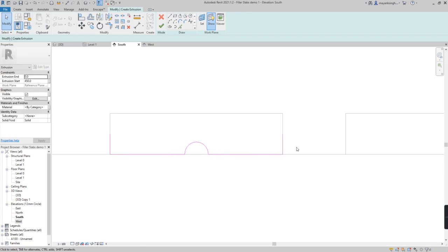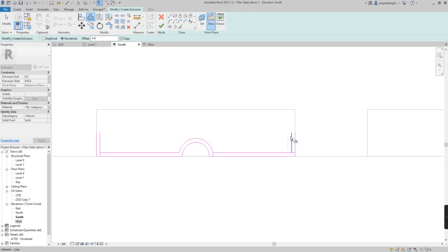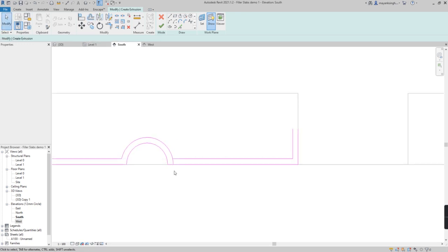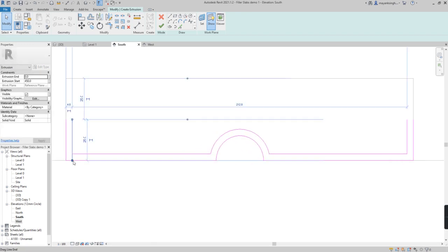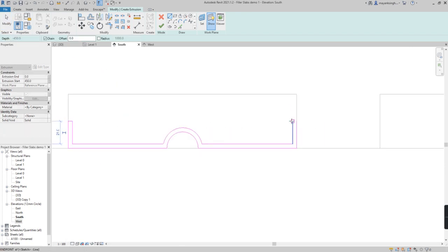Now this is nice, I will create a small offset for the thickness. Again, I'll go with 4 mm, and this is it. I'll pull back, make a proper fillet, close it, and one last thing which I like to do is have a tiny fillet radius.